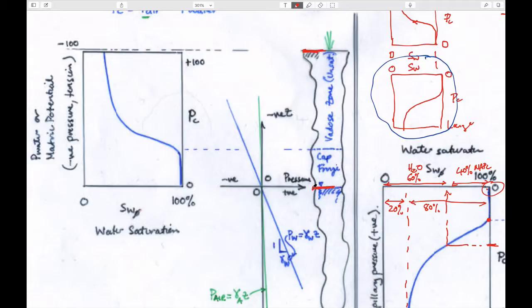What do we know about the water table? By definition, the water table is physically the location where the fluid pressure is exactly equal to the atmospheric pressure. So if we use atmospheric pressure, the pressure at the water table is 0. So again, if we're deriving fluid pressure vertically, this is 0 where it crosses this axis. And in the water below this, going down in the swimming pool, this is the same as we did before on the right-hand side.